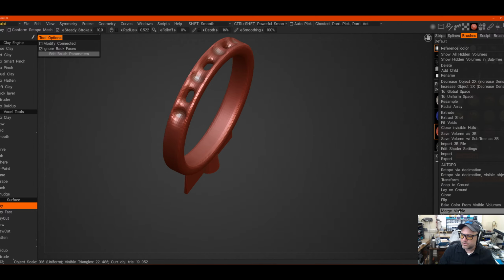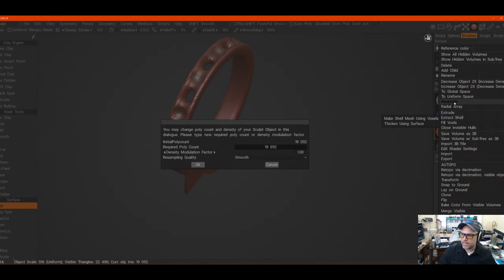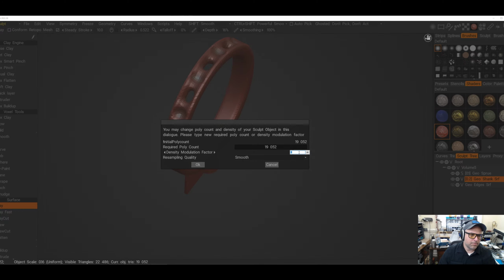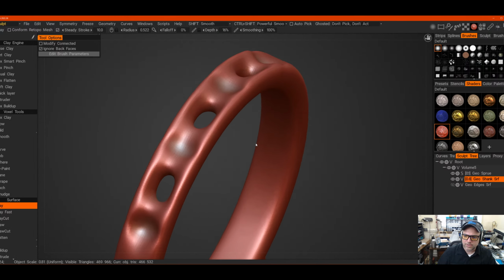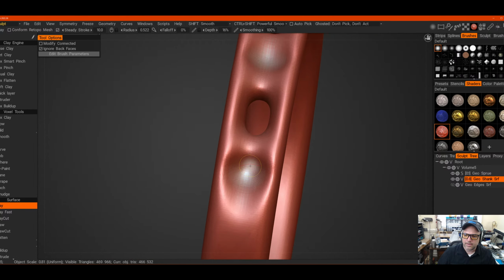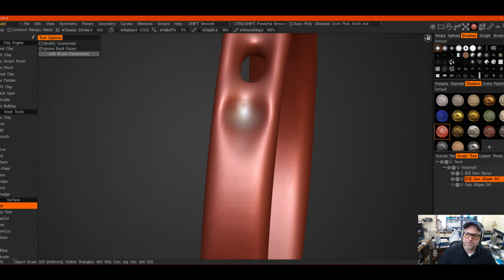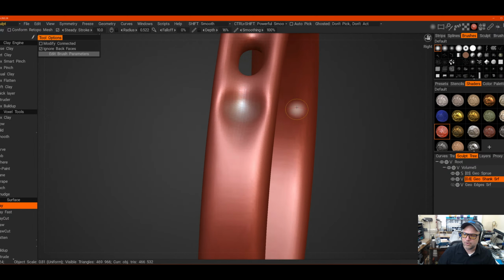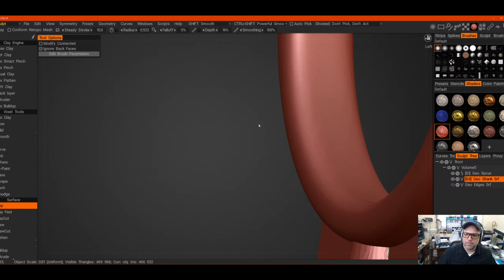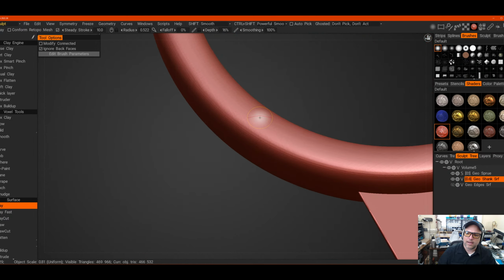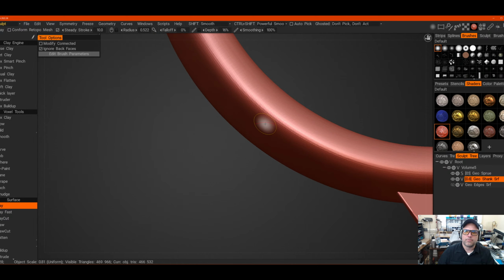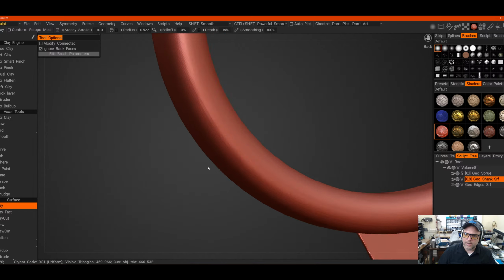Then you bring it back to resample. And what did I do? 0.2, so that's 1/5. So now I need to take it to 5 to get back to the resolution I had before. And you do that first so that when you cut your cutters and you do all that stuff, that detail will remain, but you just got this insanely fast little fillet that you would have struggled for 30 minutes in Rhino trying to get, you know, that little fillet worked in.